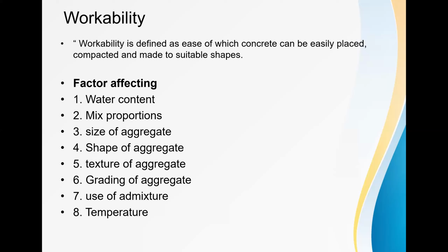Next is the grading of aggregate. The better the grading, the less the void content and the higher the workability. Use of admixtures: of course, admixtures play a vital role in the workability of the concrete. We use superplasticizers as well as plasticizers to greatly improve the workability of the concrete.